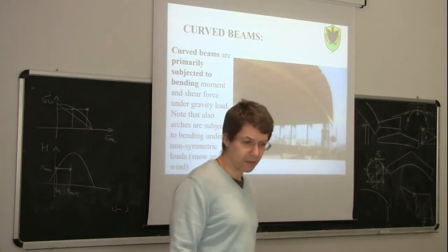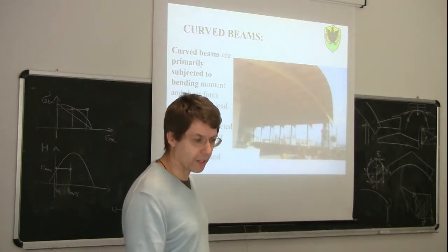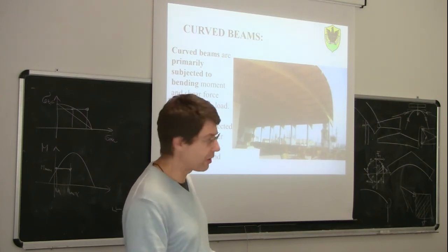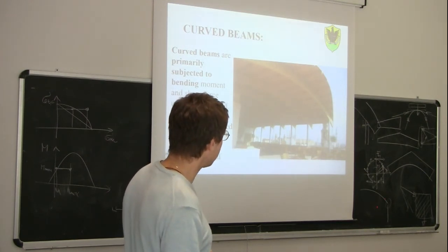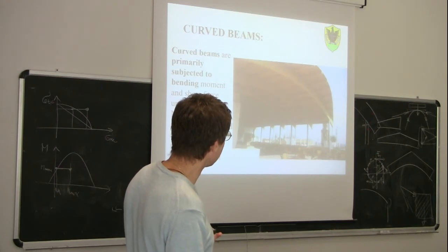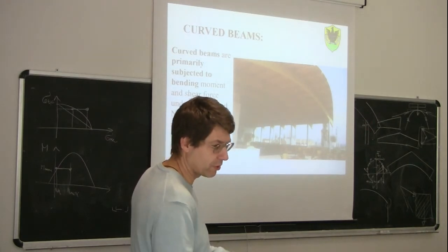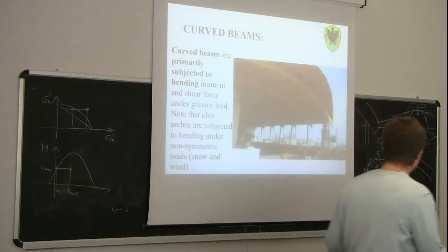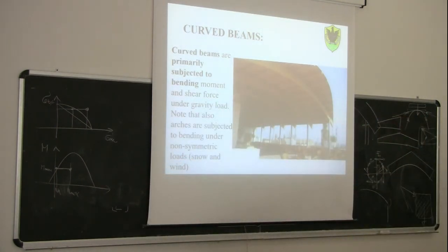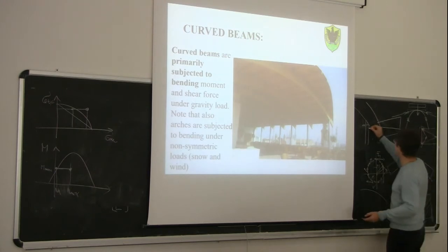It's an internal connection. It's a pin connection. What's a pin connection? Well, more or less, think about the bending moment. Is this connection able to transfer a bending moment from here to here? No, because the two members are too different. To be able to transfer a bending moment, this one should be in some way extended.